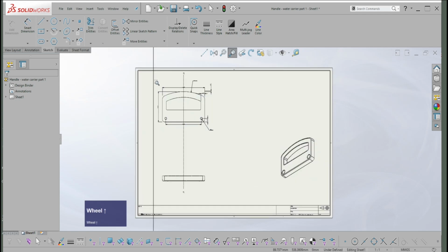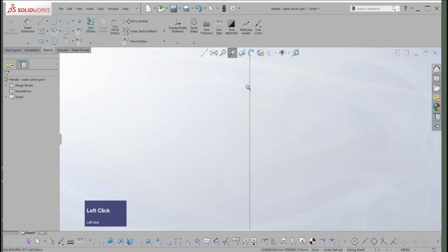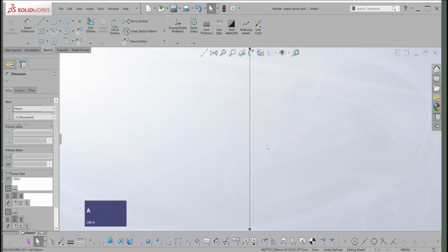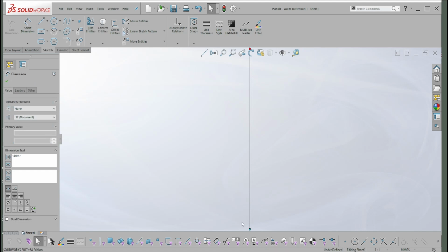So what was going on is that somehow that point that I tried to introduce was linked to something which I didn't anticipate. So by zooming out, you can see everything that's in your view. And currently, it's this line. And if I say Control A, select everything, you'll see that it's selected at the bottom. I don't know if you can see this, a little blue point, and at the top, a little red point. So an angry red point means that that's causing the problem.